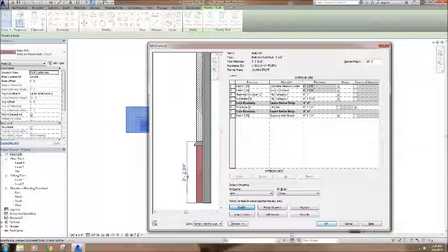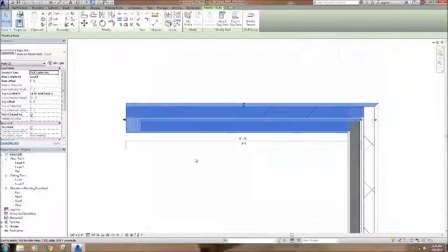If I want to change this height, I can click modify, click that little button, and then change this. Let's say I wanted it to be 3.5 feet. I could do that, and it'll change as I go along. I can create multiple split regions. I could change the material again if I wanted, and then reveals basically do the same thing as the sweep. It just cuts rather than creates a solid thing. So I'll show you what this looks like in kind of 3D here.